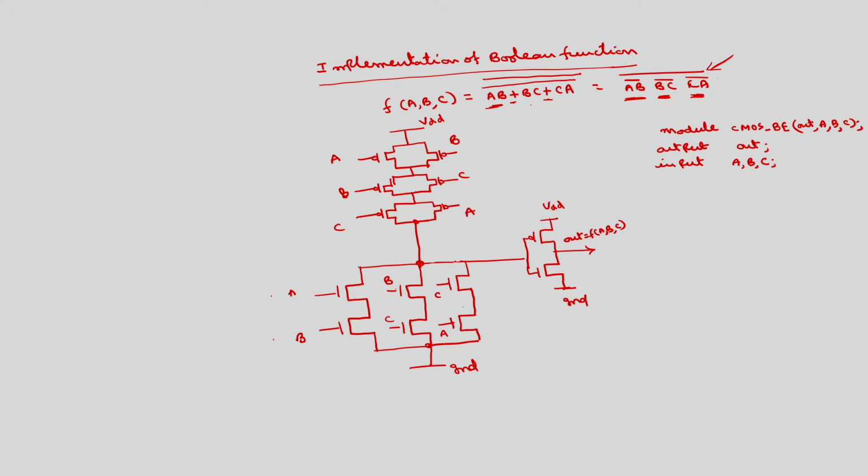This point is not accessible, here I require a wire, which I will define as wire W1. Here we require W2, W3, W4. This is VDD, this is ground, this is out; here we do not require, here this is C, this is A. This point is also wire W1, whereas here we require W5, this is W6, and here of course this is VDD.